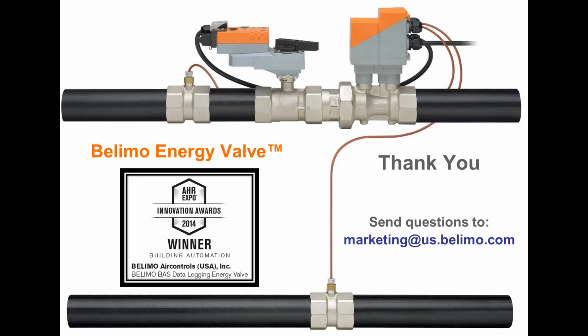Okay. Next question. When we use power control, we get better delta T performance. Is there a tipping point where I get too much delta T and the chiller would not be able to handle the extra absorbed energy? In general, we want to design our coil delta T's to match our chiller delta T's.